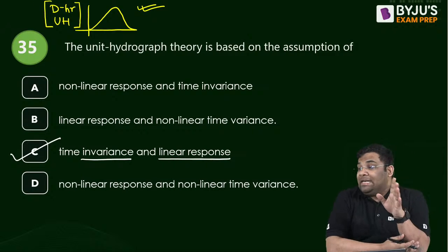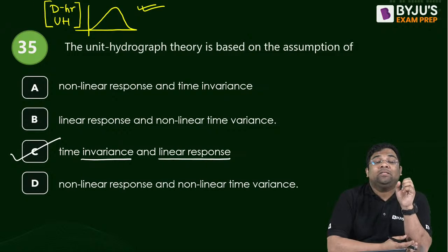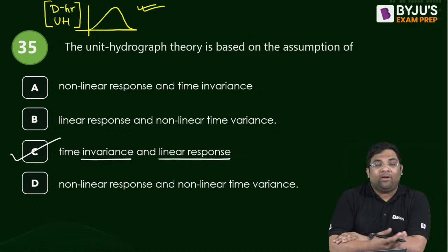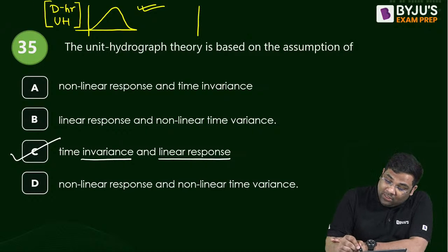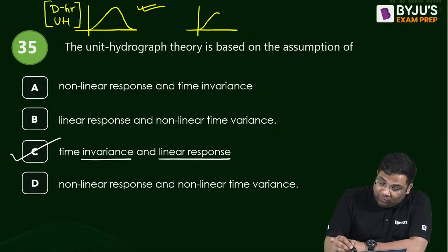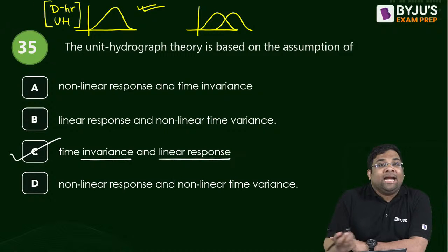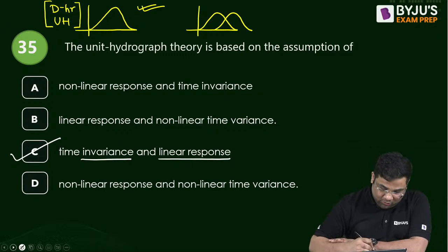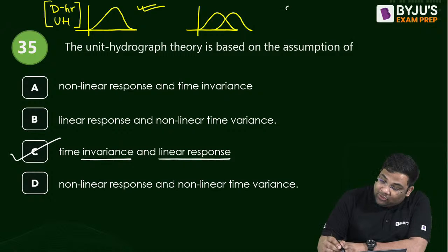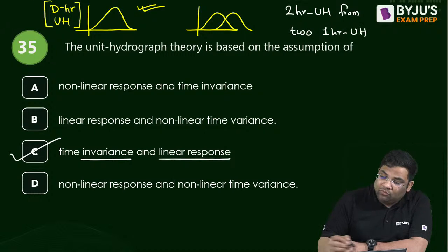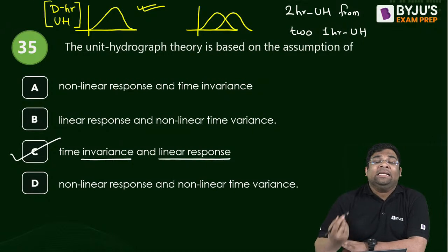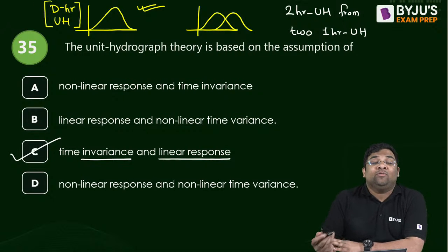And the second one is linear response. What is linear response? That you can add two discharges, right? When you are building a complex hydrograph from two hydrographs, you just add them. Or suppose I am preparing a 2-hour unit hydrograph from two 1-hour unit hydrographs, I just add them, right? So this is linear response. They are linearly related, so we can add them.